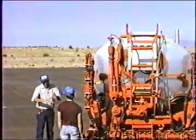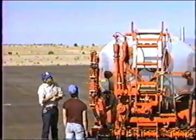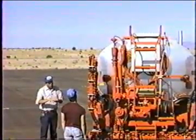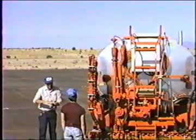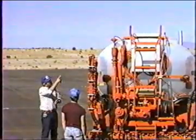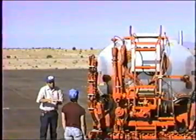That brake can pushes down on that disc. The effective area of that brake can is the same as the effective area of the disc in the valve. So if we put 10 pounds of air pressure on that air can, it takes 10 pounds of liquid pressure plus a very slight amount in order to lift that disc. And with that, we can actually regulate pressure on the whole piping system.